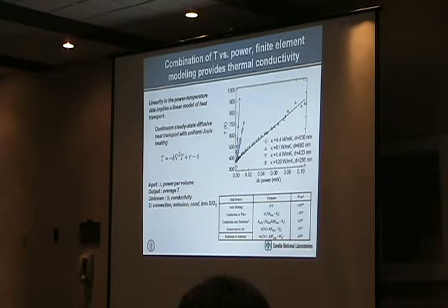He said, well, this is what I can measure. I know that there's probably going to be conduction into the contacts, some conduction probably through the SiO2 into the silicon. Of course, SiO2 is not a very good conductor. Some convection, some emission. So since we know that we are under steady state conditions, and we know how the temperature varies with the power input, can we extract the temperature profile, can we extract the thermal conductivity? And this is what we've done.